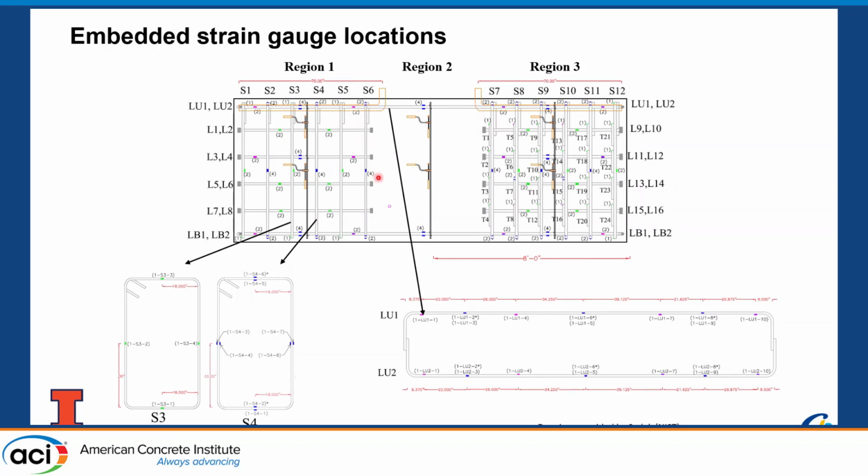Each one of these was fully reinforced and fully strain gauged on the rebar inside. And so we had access to the strain gauges embedded in there, and we used that stress that was put on the rebar to say higher strains mean ASR expansion there. Okay? I'll just show you, this is an elevation view, this is the top view in a cross section.